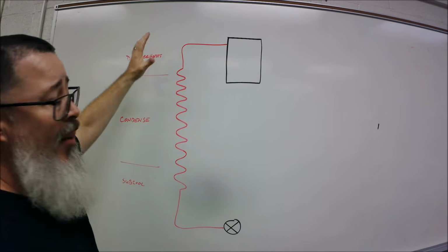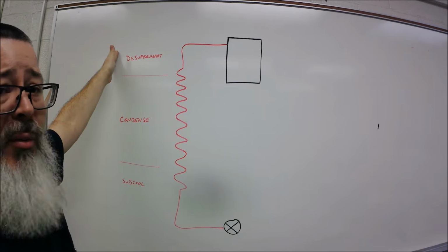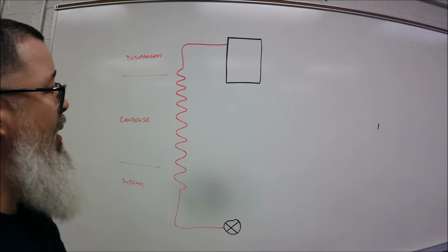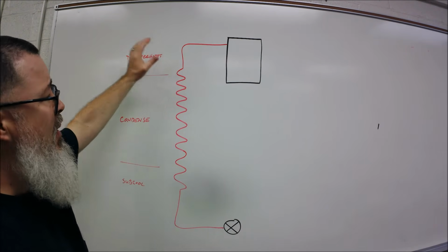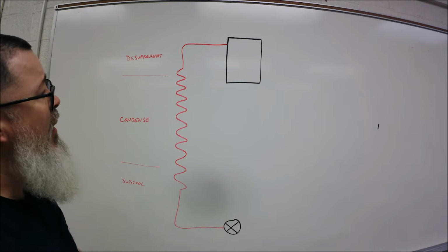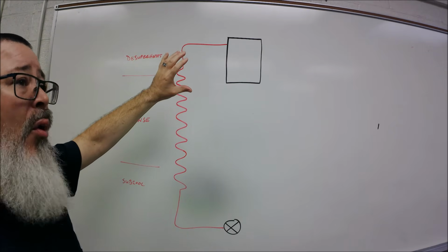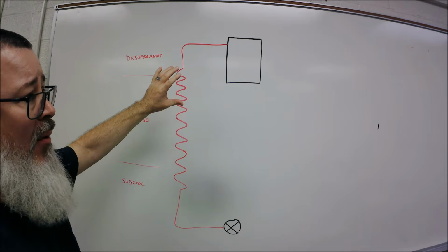The first big job of the condenser is going to be to de-superheat the refrigerant, okay? I've got it broken down: the three main jobs of your condenser are de-superheat, condense, and then we start our subcooling process, right? So as we exit the compressor, that warm refrigerant vapor is definitely 100% vapor already.